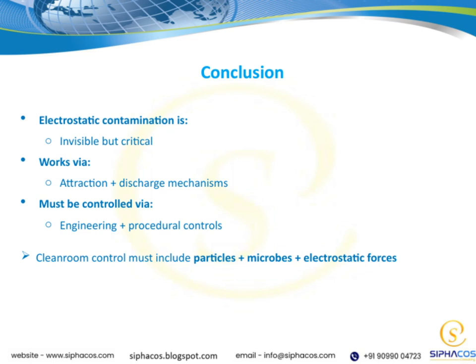Controlling these effects isn't just about awareness. It requires a combination of engineering solutions, like grounding and proper material selection, and procedural controls, such as staff training and handling protocols. And remember, maintaining a clean room isn't just about controlling particles and microbes. Electrostatic forces are equally important.